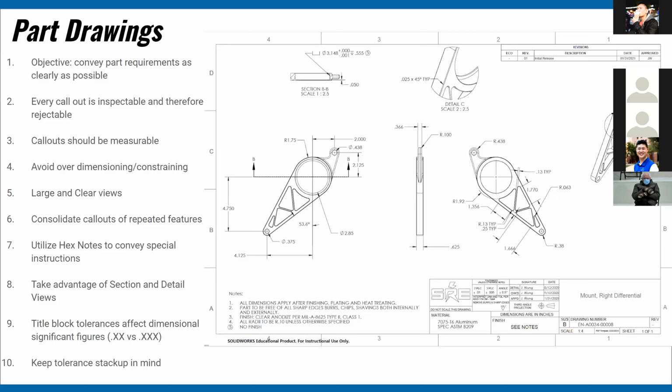And if you're thinking about a lathe, if you have a big cylinder with a bunch of notches in it, or a bung or something like that, you want to understand where the zero is going to be for the machinists, and then dimension from there. One of the big responsibilities of all engineers, particularly on this team, and for parts that we make in house but also for sponsors, is you have to really research and think about how things are going to be made, and take that into account when you're putting your dimensions in.